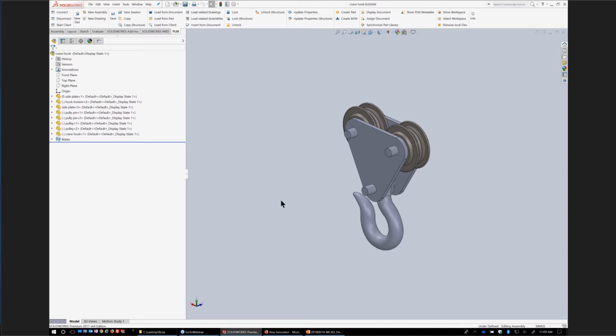When we talk about the part item, it's important to explain this, because a lot of times in the CAD world, when we say part, we're thinking in terms of the CAD file, the part file. But in this case, we're talking about the part item, or the item master, which stores all the information of the CAD file. To be able to create that, the connector allows us to do that pretty easily. Of course, we can always create the part item separately and have it linked and assigned back to the CAD document.